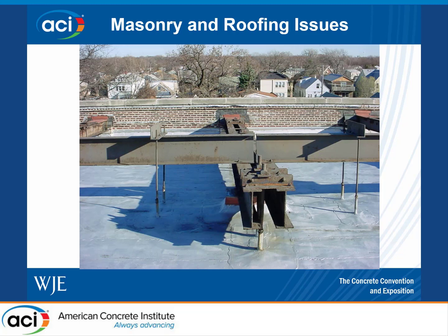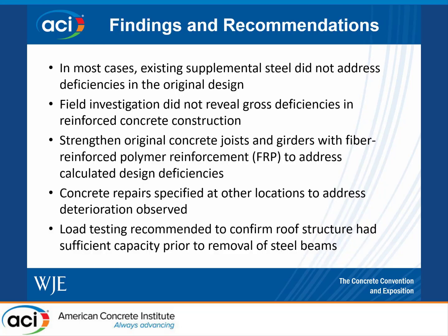The school board retained us to do an investigation and analysis of this building to determine if there were other solutions to minimize or eliminate the maintenance problems. So our analysis found that the existing supplemental steel typically did not address design deficiencies. There were some design deficiencies, but it did not warrant the amount of structural steel that was added for shoring. Our field investigation also didn't observe any gross deficiencies in the overall concrete construction. There were some issues, but again, they were more isolated conditions that we were addressing.